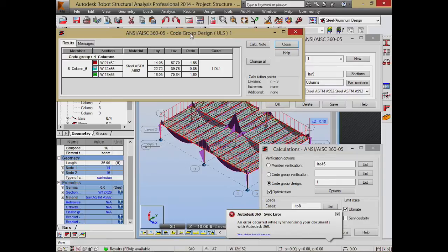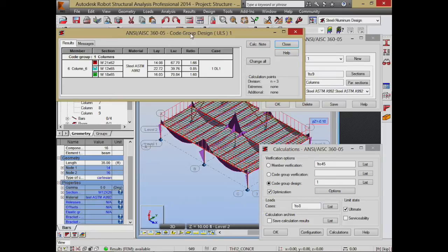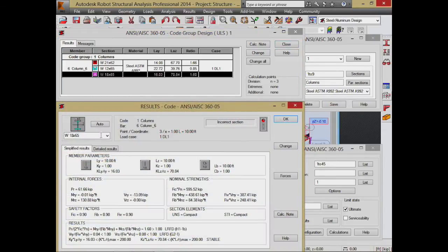It's interesting. The ratios are funny. It considers that to be the optimum. If I switch to that one, it won't be right. Although I'm wondering what's going on with the ratio, because that looks like a funny number to me. I would expect that to be actually this. No, that's the next size up. That's still overstressed. It's confusing me about what it's telling me right now. Bigger flange, same weight, should be okay. I don't know why the ratio is that way. A little strange. But I can go ahead and go changing through some of these different things.